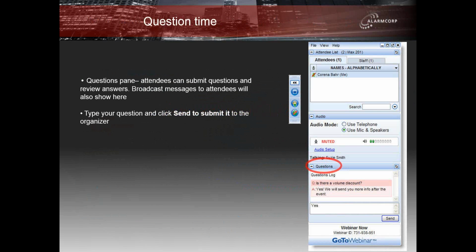Let's answer some of the questions. If you have a question now, this is the time to type it and hit send. Okay, the first one. What is a typical range for a WDR camera? The range that is typically shown on a datasheet for a camera to be classified as WDR is normally in excess of 70 dB, extending all the way through to 130 dB.